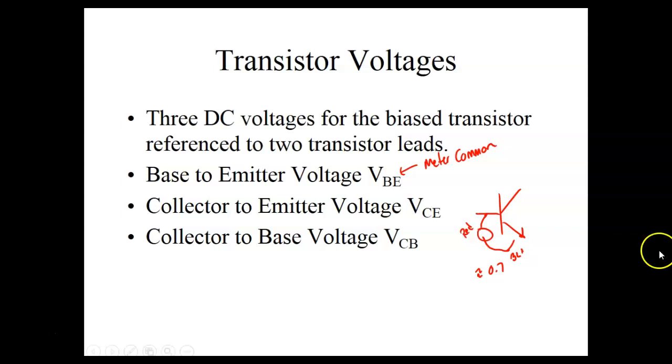The collector to base voltage, which means we would actually put this on the lead or a component connected to the lead. That bothers me too, where I'll come over here and I'll have this nice big resistor sitting right there, and this little old transistor sitting down here. These leads are close together, and you're trying to get between these guys when I've got a resistor over here on the base, so I could put my lead on the big nice metal thing on the resistor, and I could go to the big nice metal connector on that. So that's one thing you're going to learn on transistors. It's very hard to measure across the lead.